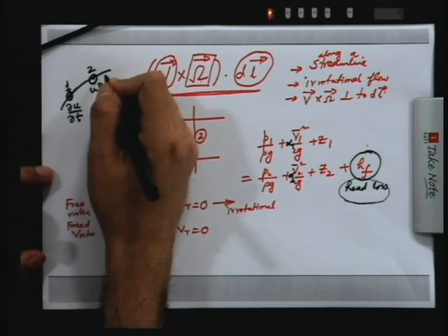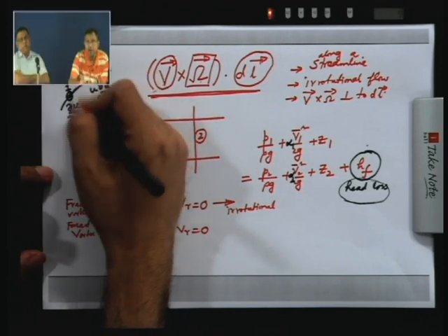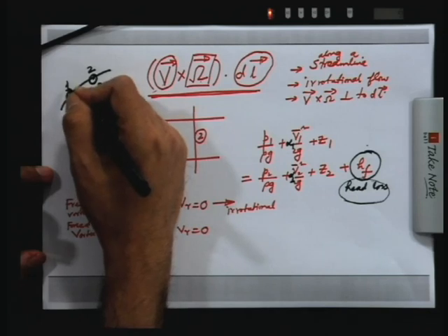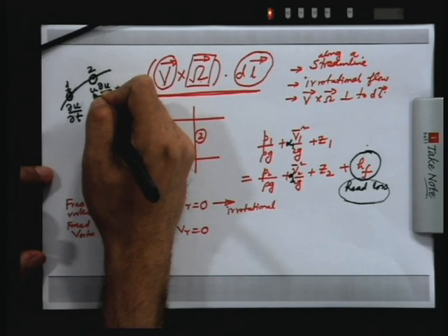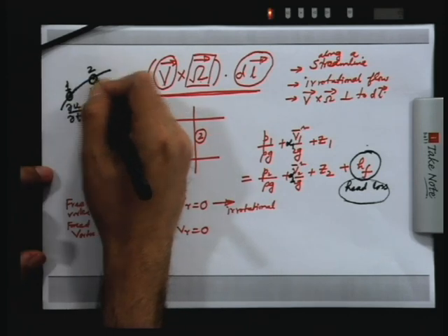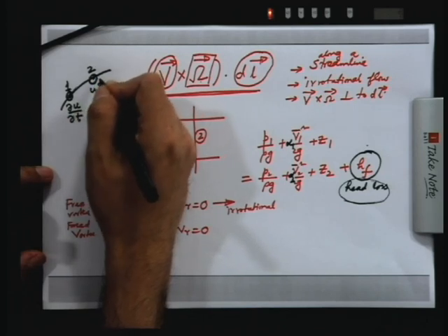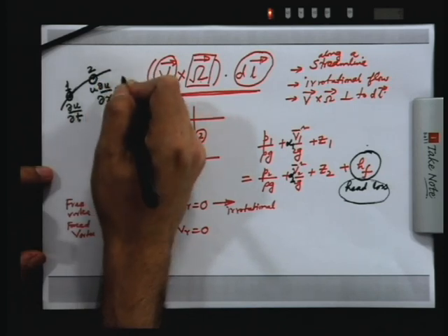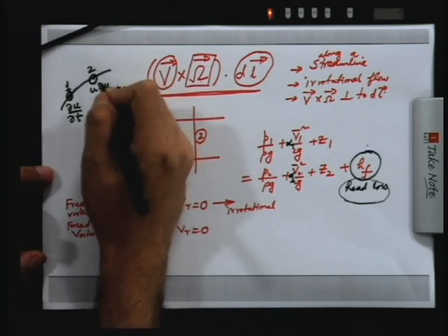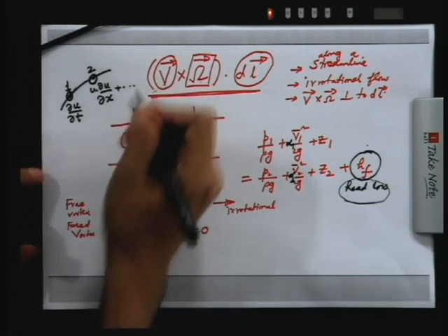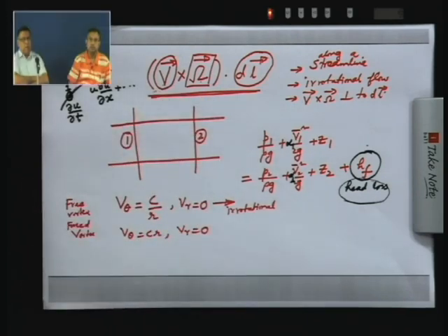So, the change in velocity of the particle is a combined effect of the change in velocity at a given position due to change in time, that is the temporal component, and because of the change in position the particle finds a new velocity field. That is because of advection of the particle, and that is called the convective component. The total acceleration is the sum total of these two effects. Okay, sir, thank you.